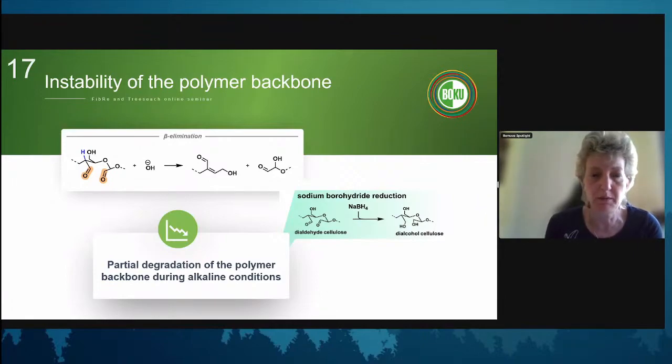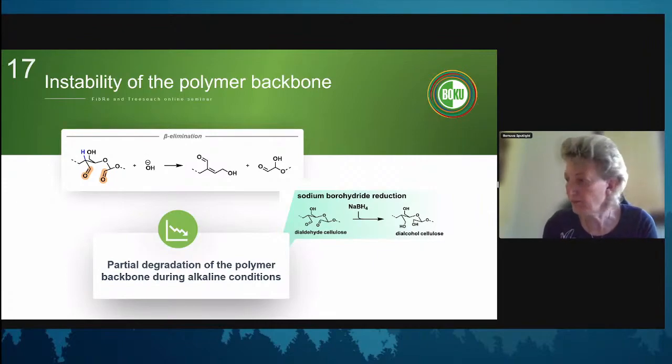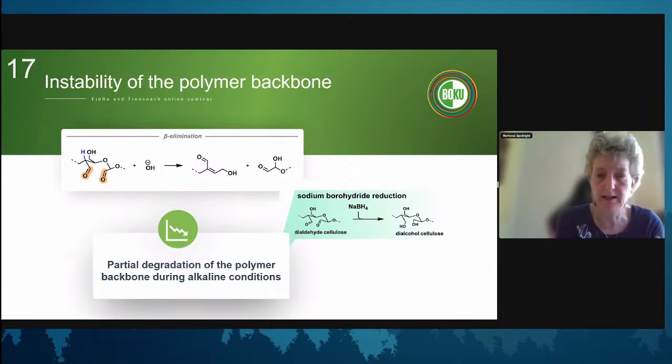The solvents for viscosity measurements in the pulp and paper industry are usually highly alkaline. And if we went in there with an oxidized cellulose, we would degrade the cellulose during dissolution, and we would not be able to get the original molar mass or viscosity of that sample. So the classical workaround is, okay, let's do a sodium borohydride reduction, and then we arrive at more or less the original number. Yes, that works for slightly oxidized celluloses, usually in a good way.